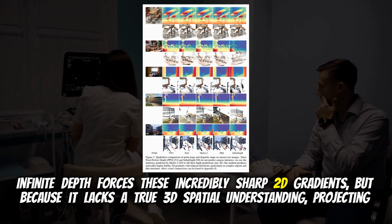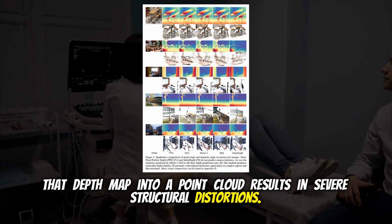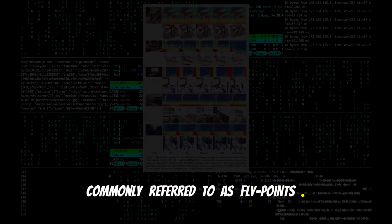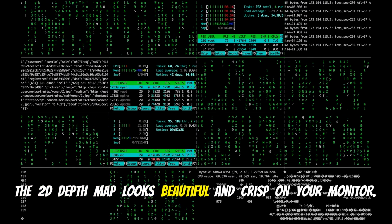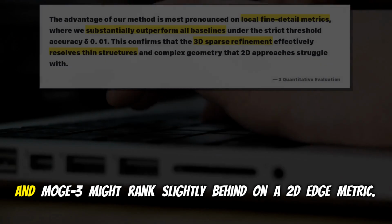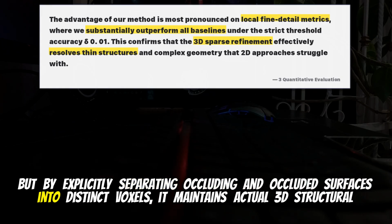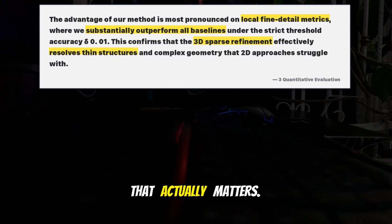InfiniDepth forces these incredibly sharp 2D gradients, but because it lacks a true 3D spatial understanding, projecting that depth map into a point cloud results in severe structural distortions. Like what? You end up with massive strings of artifact points connecting foreground objects to background environments, commonly referred to as fly points. Oh, that is the ultimate trap for an ML engineer. It really is. You evaluate a model, the 2D depth map looks beautiful and crisp on your monitor, but the moment you feed that data into a robotics pipeline, your robot tries to navigate through a room filled with invisible, smeared geometric webs. Exactly. And MoGe-3 might rank slightly behind on a 2D edge metric, but by explicitly separating occluding and occluded surfaces into distinct voxels, it maintains actual 3D structural integrity. Which, for any practical application, robotics, augmented reality, novel view synthesis, 3D integrity is the only metric that actually matters. It's the only one you can actually use.